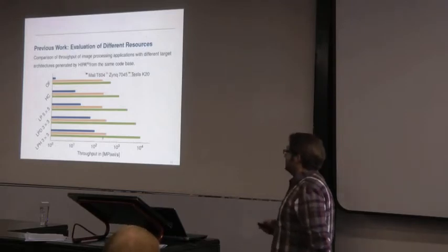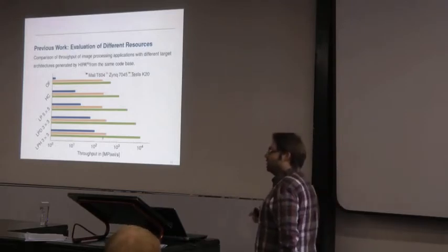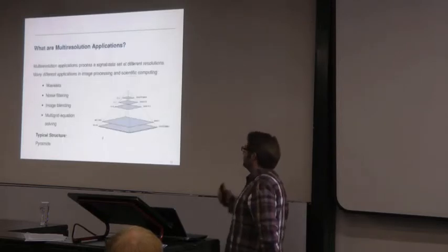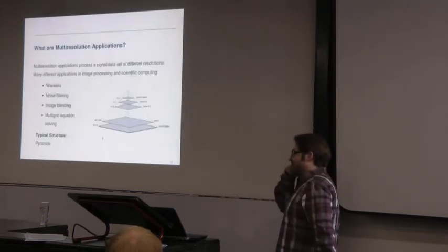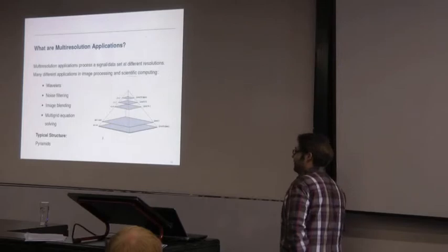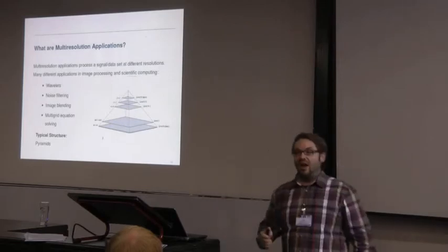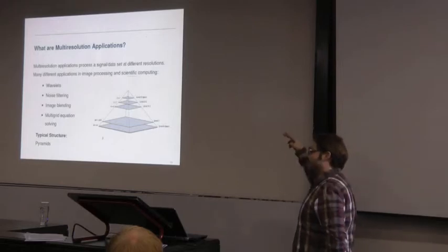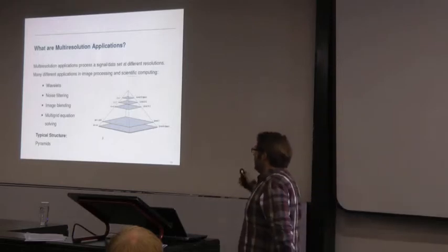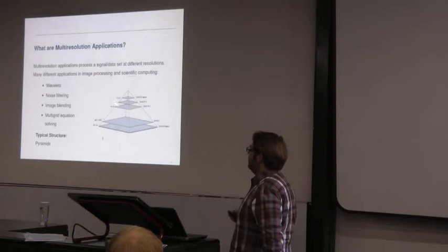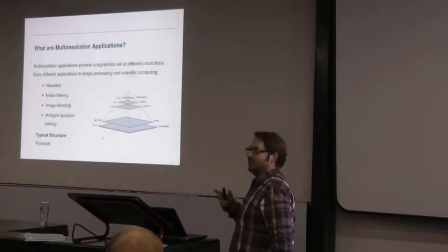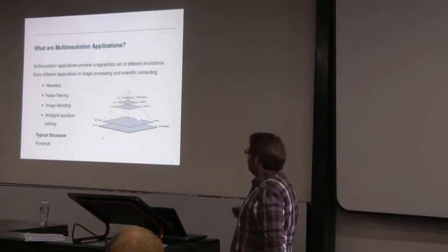So we thought Harris-Horner and optical flow are already quite challenging, so we're going to put some more resources into the FPGA and expand it to multi-resolution applications. What are multi-resolution applications? Multi-resolution applications analyze designs on several different levels of resolution. Typical applications are wavelets, noise filtering, image blending, multi-grid equation solving, and you have this typical structure, meaning you have